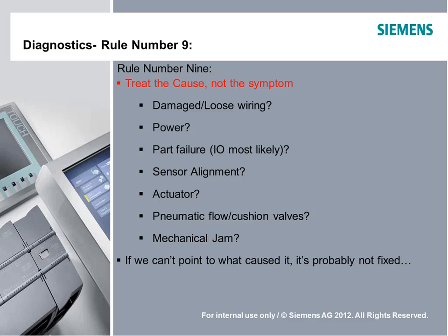So if somebody dead-shorts a sensor on the far end of the machine, rather than shutting down the whole machine, it just shuts down that 10-amp segment we've isolated and keeps the PLC, the HMI, and all the diagnostic tools up. That makes a lot of sense for isolating problematic areas.